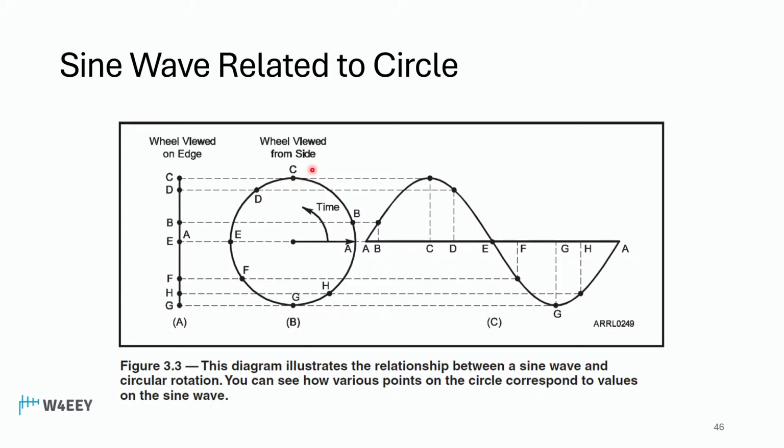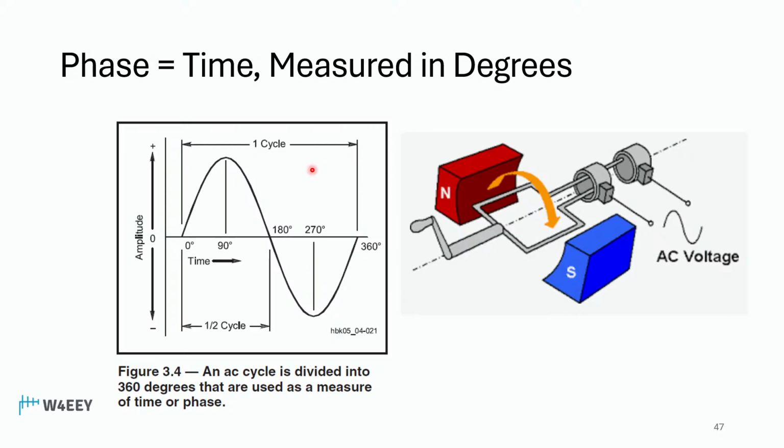There's a parallel in electrical generation. Here's a reason why this is so important, so useful. This is a highly simplified picture of an alternating current generator. We've got a loop of wire and some slip rings here, and a north and south magnet. As we turn this coil, we're going to be generating an AC voltage as an output. And again, we see what's going on here: 0, 90, 180, 360, and every place in between.